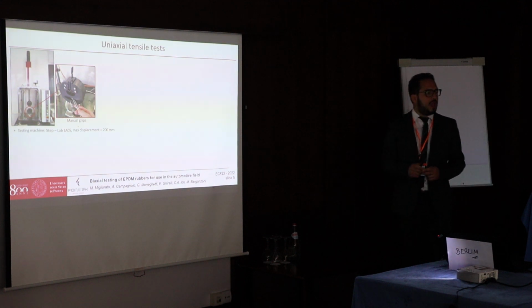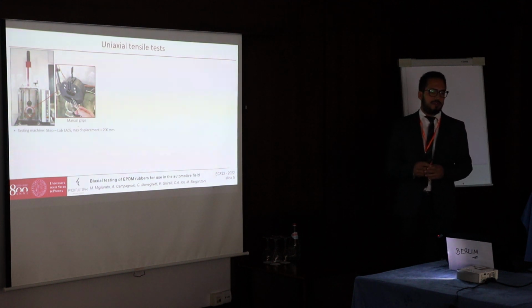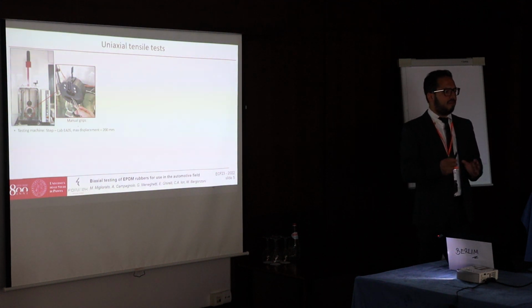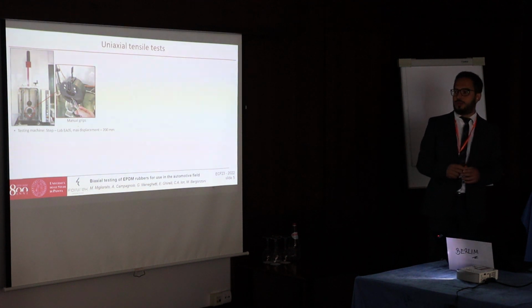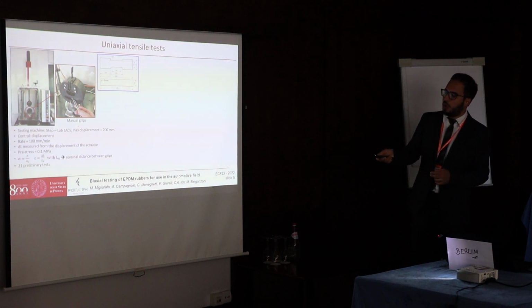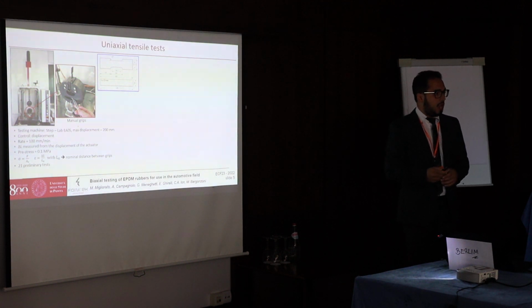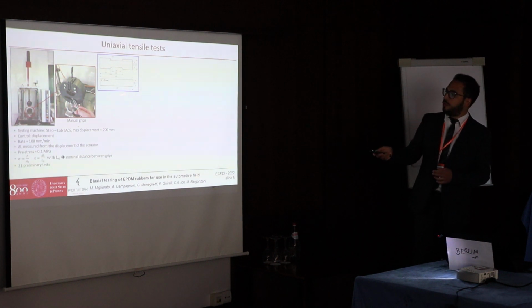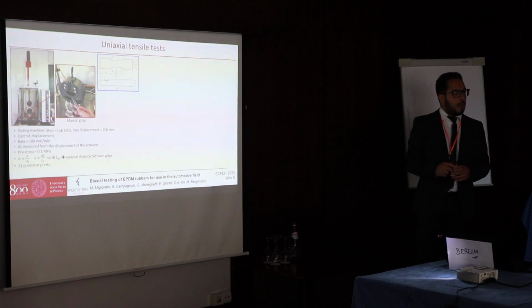First of all, uniaxial tensile tests have been performed. However, given the impossibility to adopt specimen geometry according to international standards due to the reduced stroke of our testing machines, several specimen geometries have been investigated.